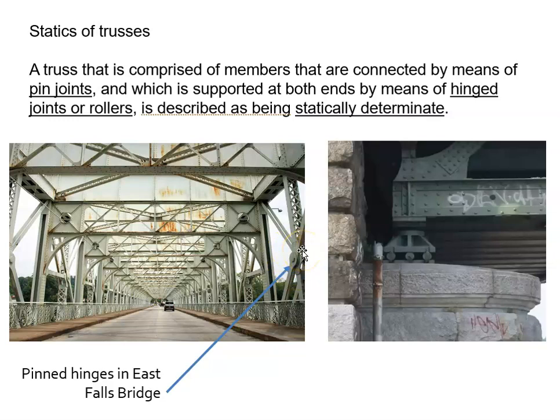It was kind of an interesting case where the mathematicians or the engineers that came up with the formulas made the assumption on the pin joints, which is kind of a theoretical assumption. It didn't truly mean that they needed to be pinned, but for math purposes, they needed something to fill in there. Some assumption had to be made. But then, interestingly, the builders followed suit with the formula, and they started pinning them all.